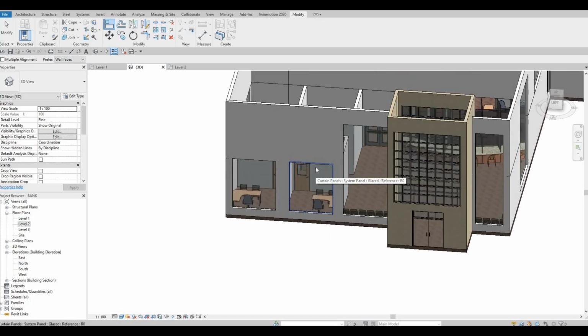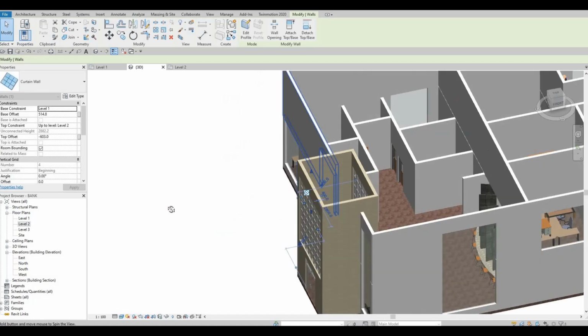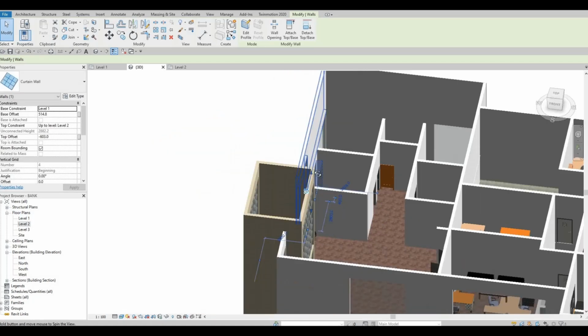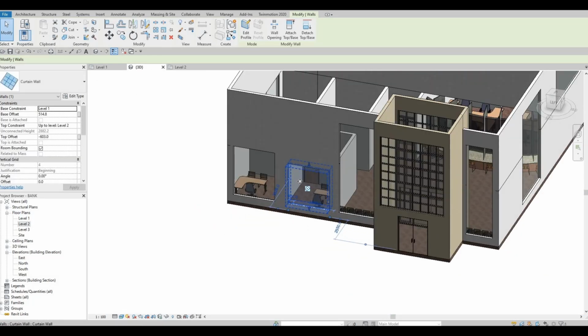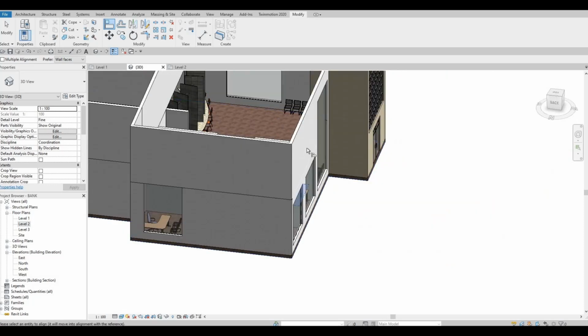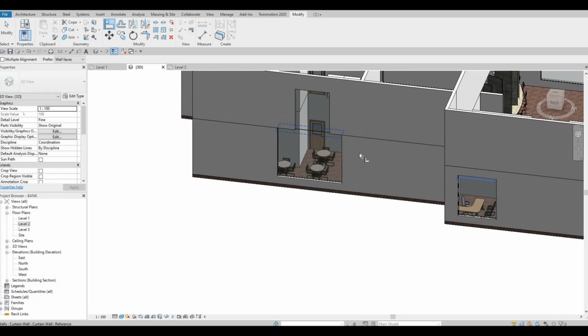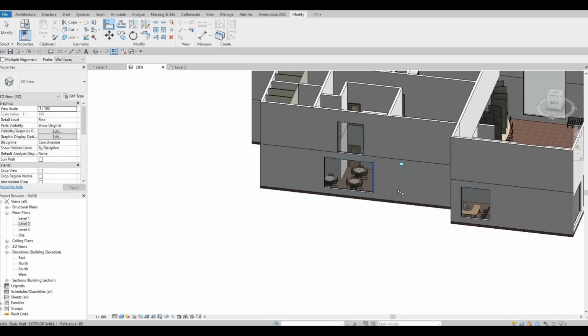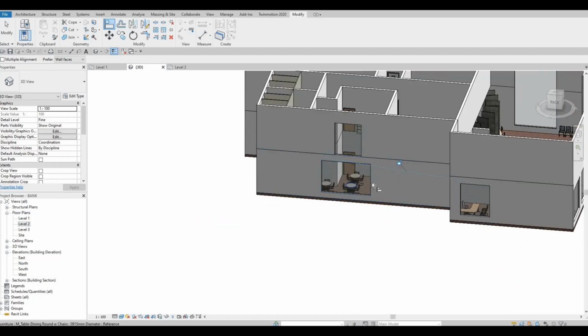And then now I'm gonna select this one, this curtain wall, and I'm going to pull it down as well. Same idea, it needs some room for mechanical, electrical, and piping to go all around here. So we just need to give it some space. And then because it also has ceiling as well. Most of the time in an office setting, it's a drop ceiling, so